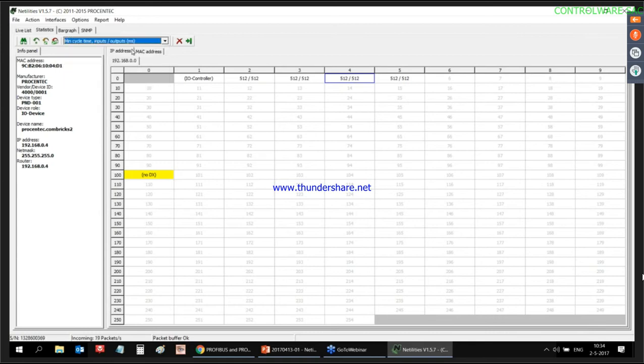And I can also see the minimum cycle time and maximum cycle time. And this is important and interesting information because this is the current cycle time, but the min and max cycle time apparently have a deviation, as you can see. And that means that something has happened in this network. Something has caused the cycle times to change, which means that probably some packets were missed. And this is interesting information for troubleshooting.